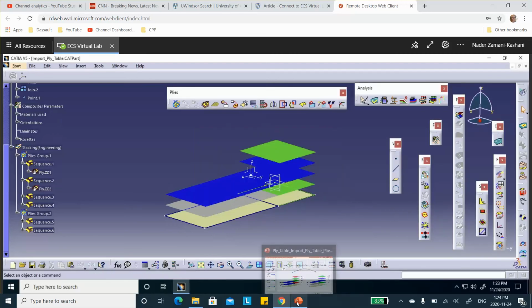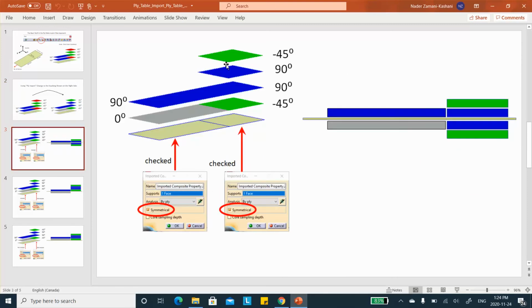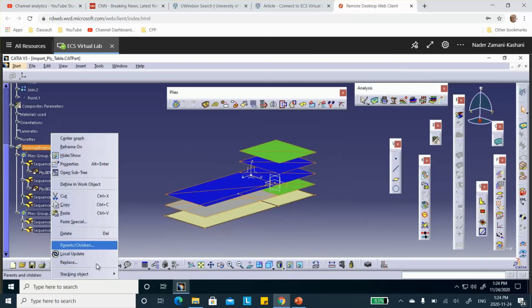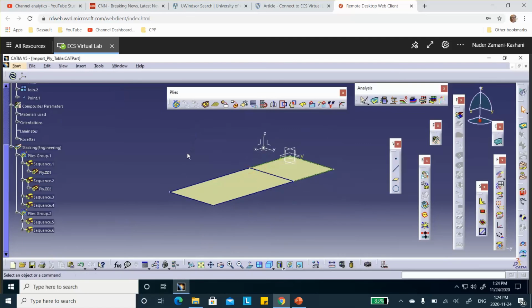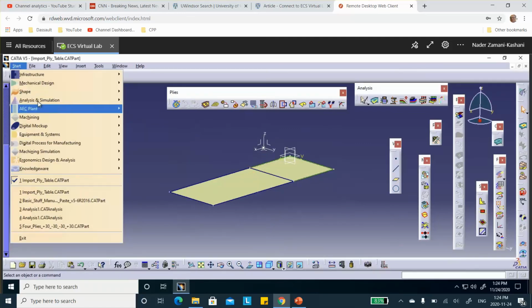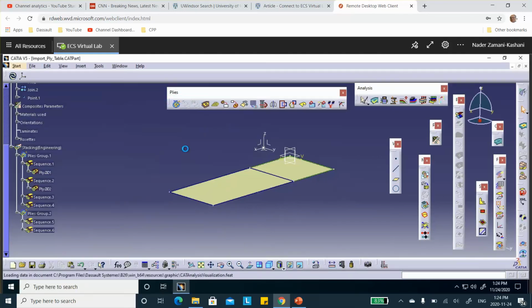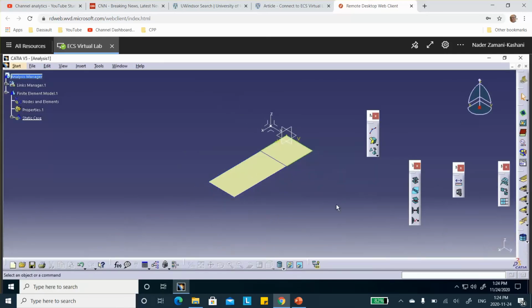Okay, so let's go ahead and do an analysis of this thing that we created. We'll get to that in a minute. So we're done here. As a matter of fact, I can go ahead and delete that entire figure here, or exploded view. All right, good. Now we're going to go to advanced meshing tools, because I want to use a fancy mesh, a rectangular type element. This is a surface mesher. I don't want to use the ugly triangular mesh.